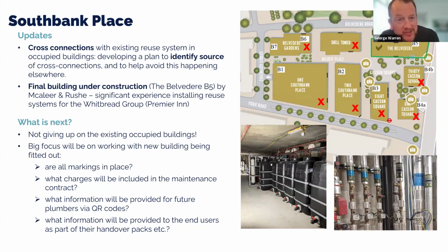All of them incorporated reuse. Unfortunately, the majority, in fact, the ones that you can see there with an X next to them, they've incorporated reuse, but there's been a series of issues associated with the reuse scheme. Please don't get too alarmed. Most of the situations tend to be situated around the connection of foul water into the grey water system, i.e. grey water recycling should just be collecting that off sinks and showers, but it appears that there's been some misconnections so that it's more than just sinks and showers that are connecting into it, which leads to problems at the treatment element.